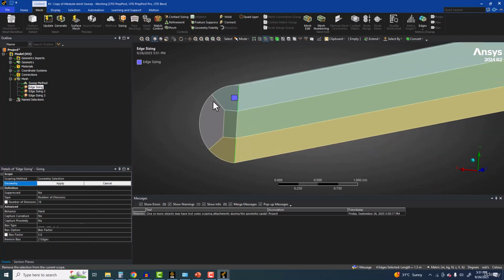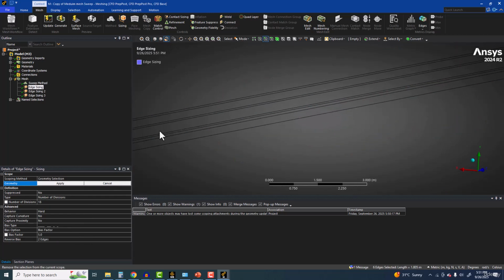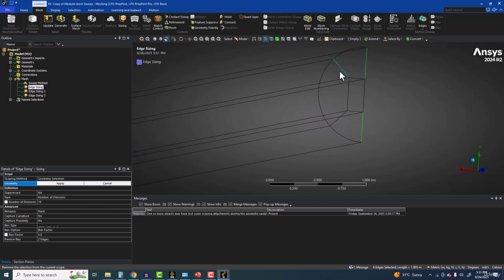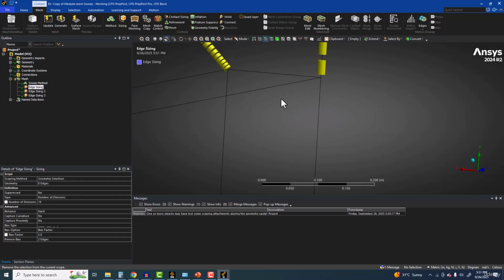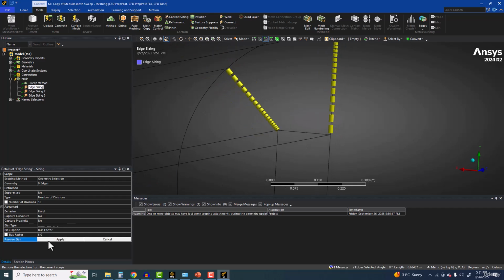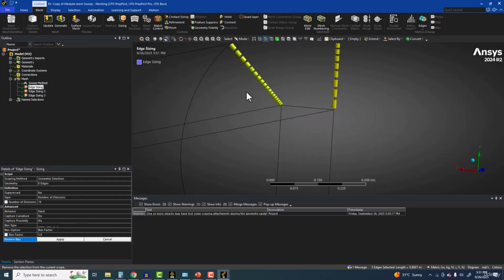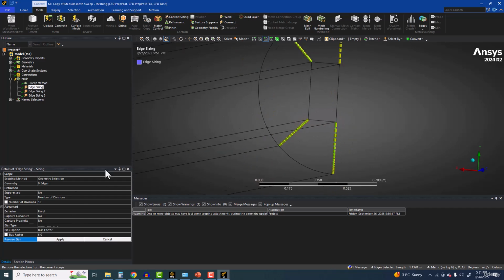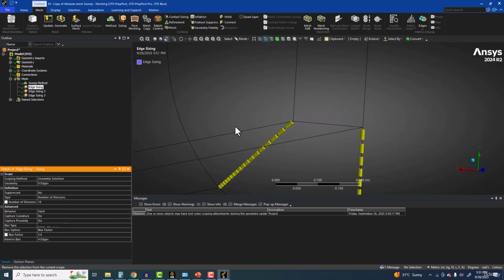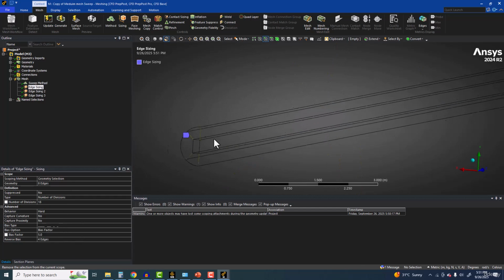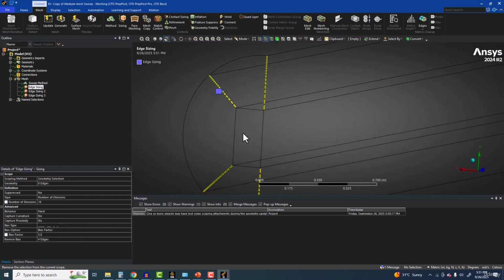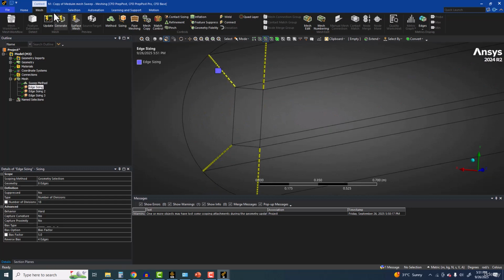Okay, so I think we missed these lines from the edges in the selection. So you have to press the control key and then select them. So now 8 edges are there, and their biasing is opposite. So you can correct that one, or you can directly reverse the second biasing type. You can go to the second biasing type if everything is in the opposite direction. Now it is corrected.